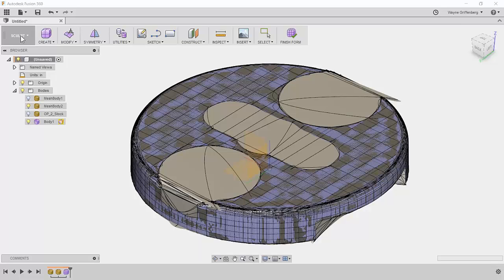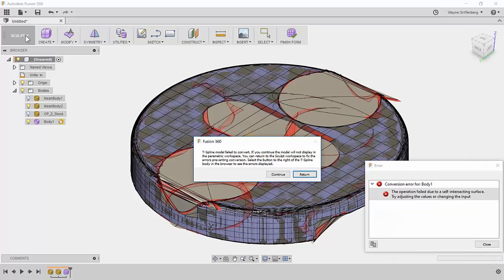So we had a couple of questions pop up. One was somebody working with scan data and working with 2 to 3 million triangles. You are pushing the limits of what Fusion will handle today. I'm told it will handle 500,000 triangles quite well, and then when you're starting to get to 1 million triangles, it'll handle it, but you're going to see some lag. So we've certainly got some work to do to expand the number of triangles. If you're watching this recording in 2 years, that number's probably changed, but that's where it's at live today.